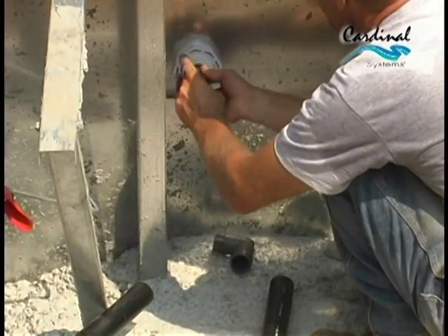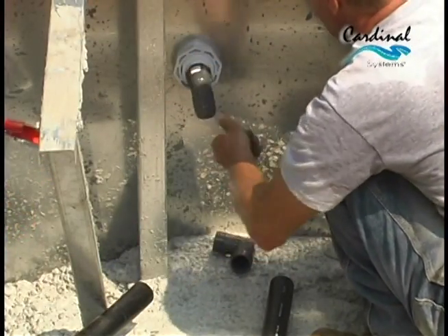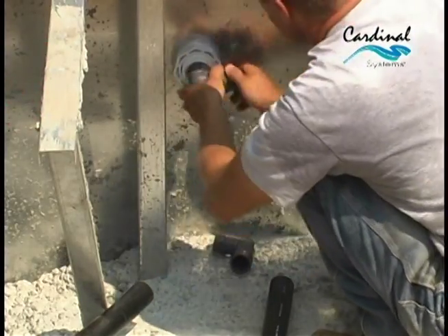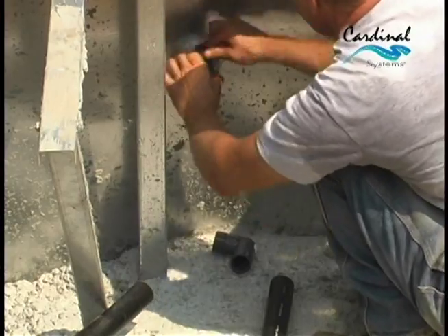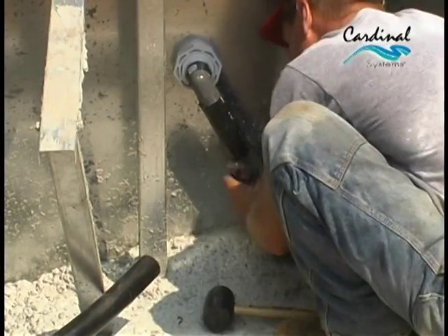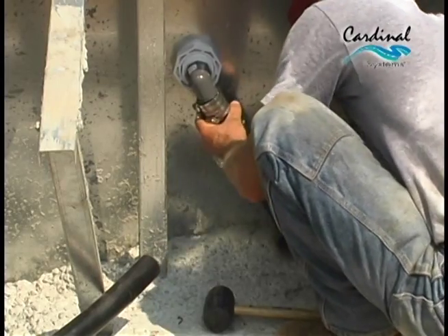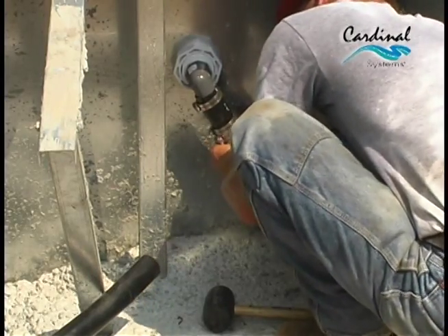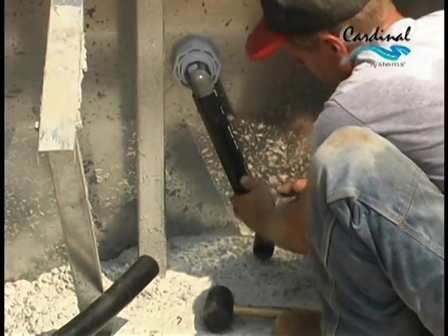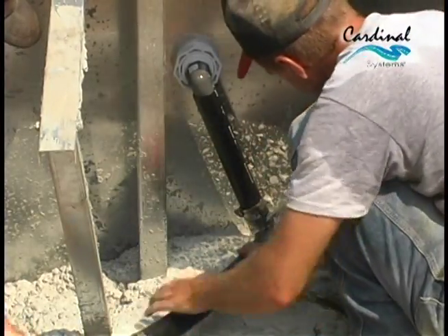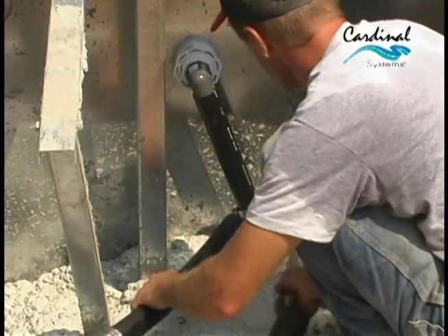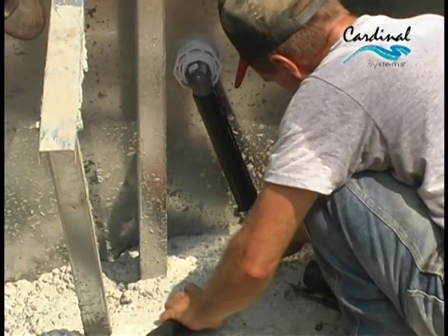Next, install the cleaner line. This is a high-pressure line. Flexible PVC is not recommended for plumbing this line. Once again, limit kinking or bending by adding elbows to bring the line immediately down to the concrete collar level.